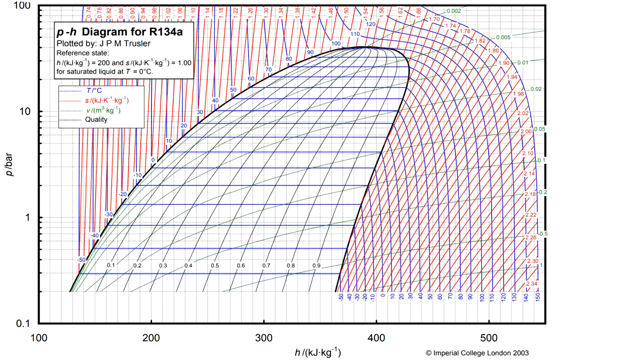Why enthalpy is such an important value in the cooling cycles is because the expansion in the expansion valve, the throttling, is an isenthalpic process. So in this diagram it would be a vertical line. Then what other lines do we have here? The black one is the saturated liquid and vapor curve with the critical point in the highest place. Then inside the vapor dome we have light black lines of values of the steam quality.